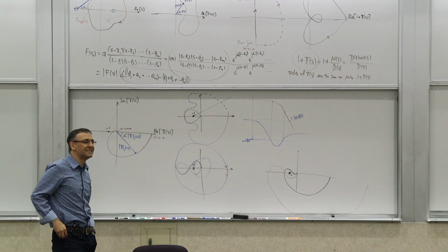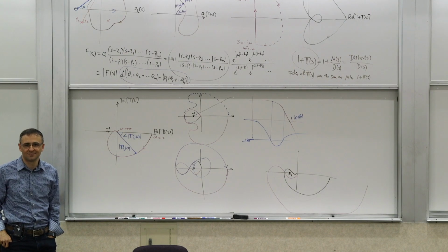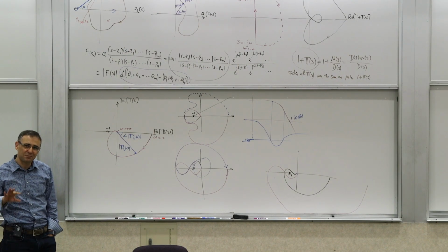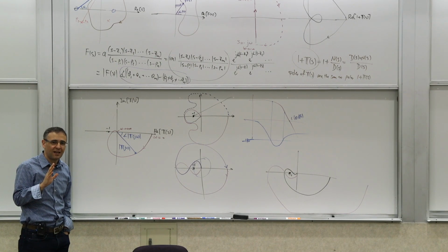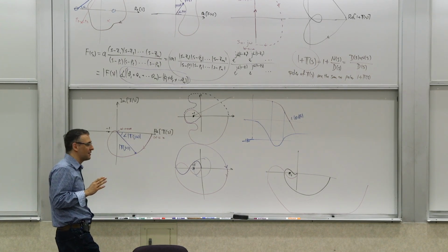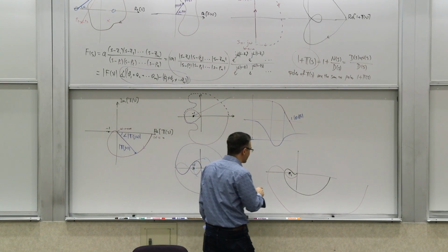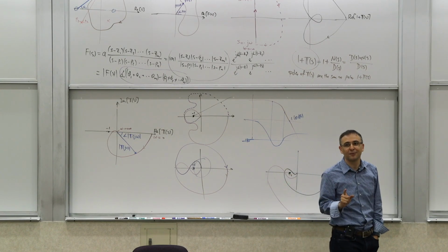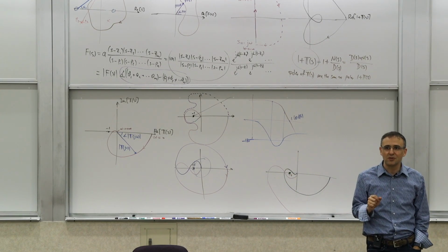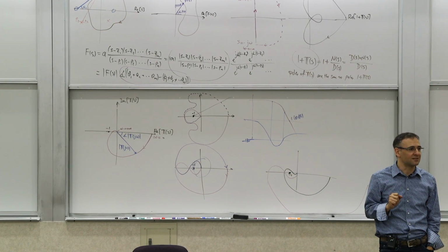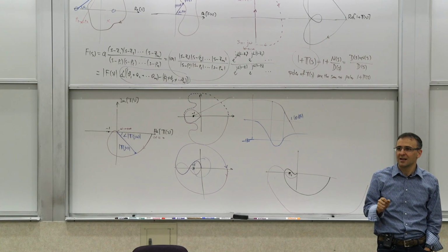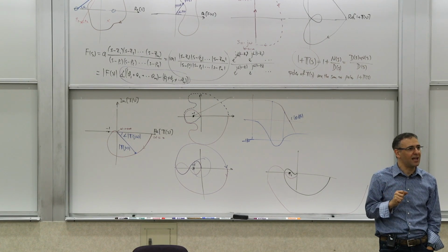These things are called conditionally stable. So this is a special kind of stability. Now, why is it a special kind of stability? If you're designing something that's stable like this, you have to be very careful, because if your gain drops for whatever reason, let's say you have a nonlinear system or something like that, then it becomes a challenge.